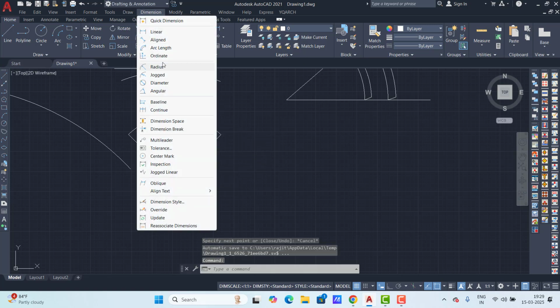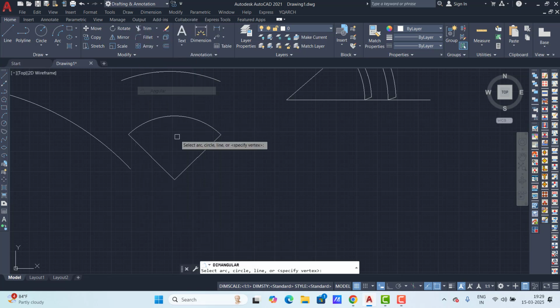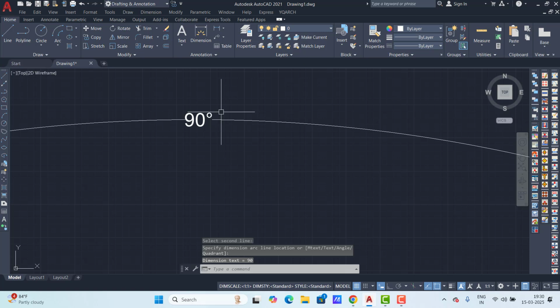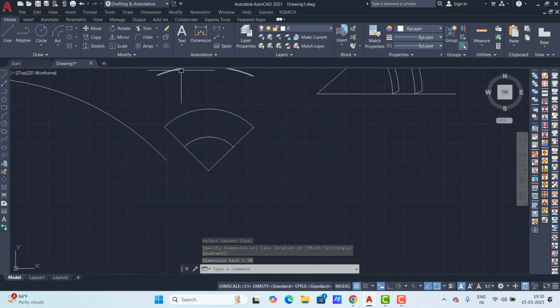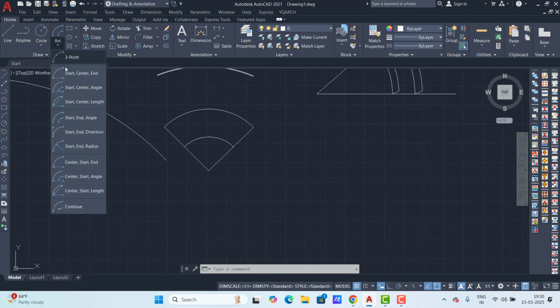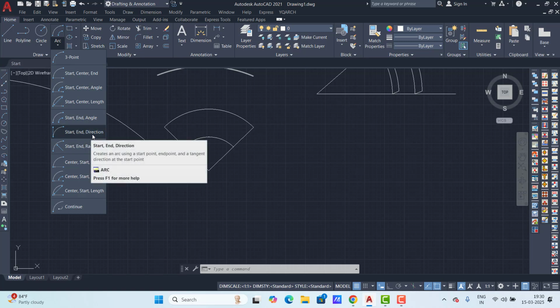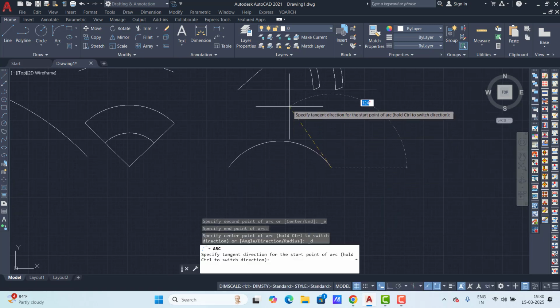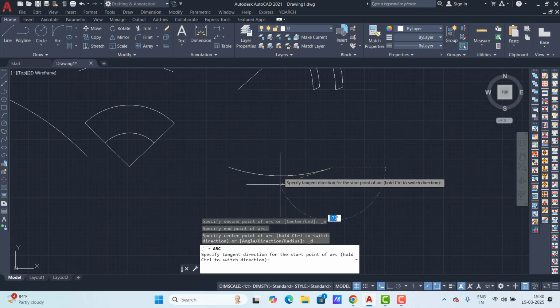So here I have one line. If you select this line, you see a single line. I want to delete this line from here to here. Okay. If there is no crossing object, you can unclick the center between some part. If you want to do the break, we go to modify and select the break command.